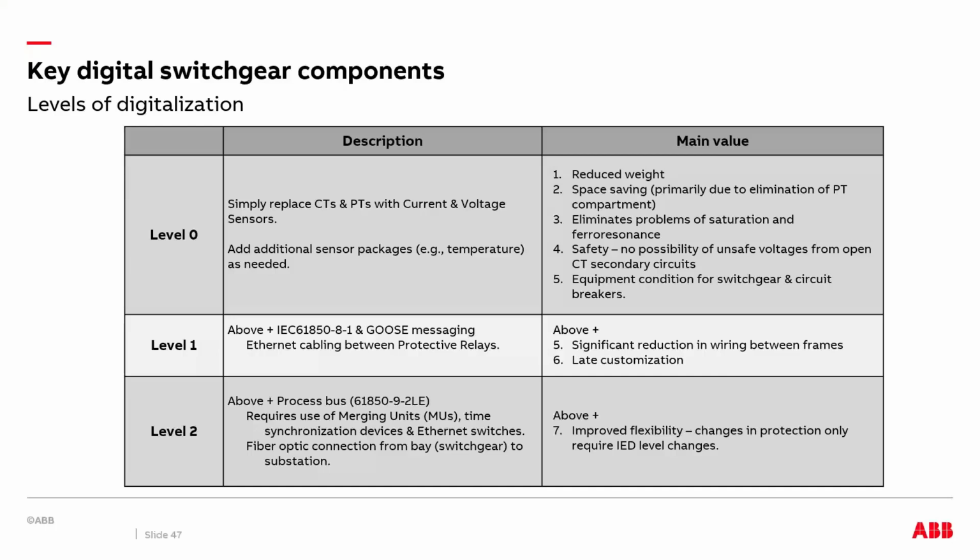Now, we could take it a level up if we are comfortable with this and introduce IEC 61850-8-1, which includes MMS, the Manufacturing Message Specification. If you want remote control or you want to enable SCADA in your system, you're going to have a relay equipped with IEC 61850-8-1, and it's going to talk with the SCADA system.